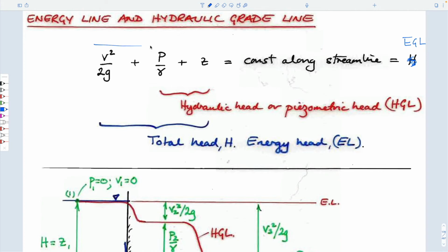We can describe the energy, which is all three of these terms together. These aren't units of energy. Energy would be joules, which is Newton meters. So these are units of length, so they're not Newton meters. But I guess this is energy per unit volume. Per unit volume of water. And so Z is energy per unit volume of water.